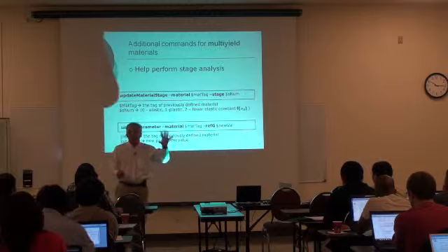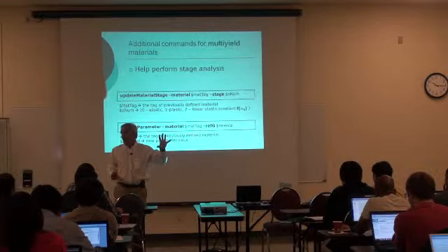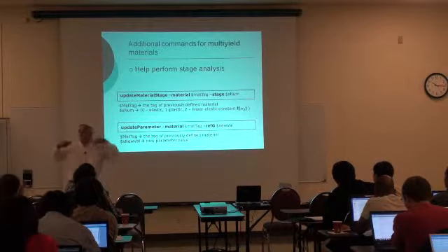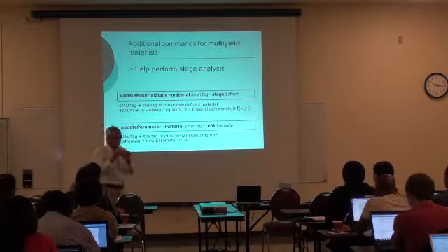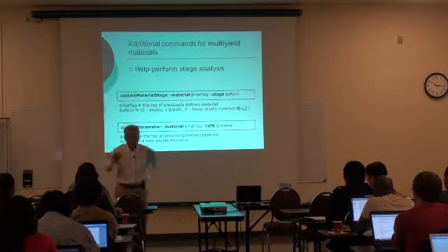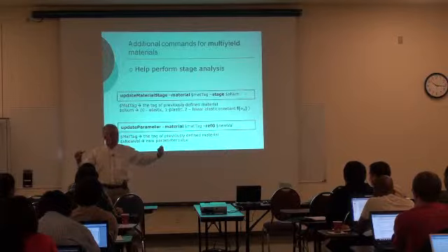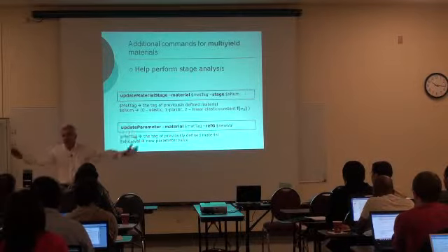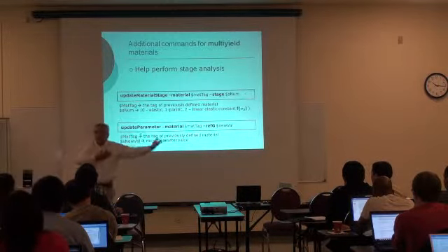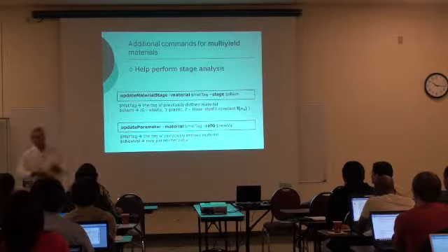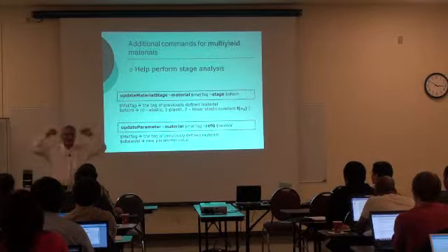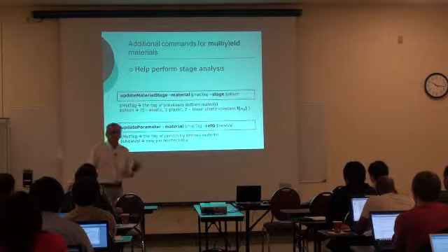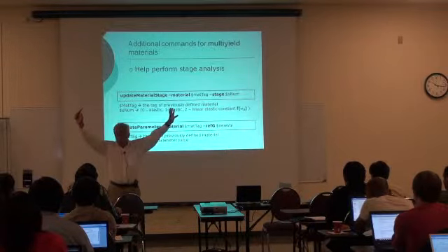You cannot set immediately the material as elastoplastic and then boom, apply gravity in one step. If you want to do that, the correct way is to start with one layer of elements, very thin, then assume that the material is elastoplastic. Then apply another layer of soil and build your soil domain like it happened in nature. Very different is to start with a mesh and say, gravity, go.